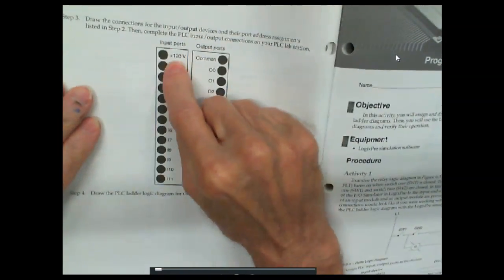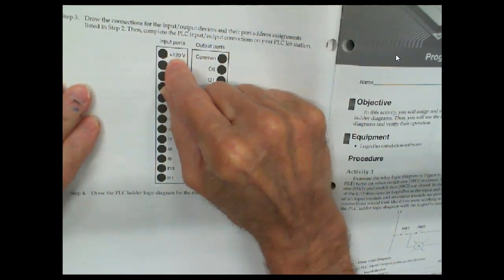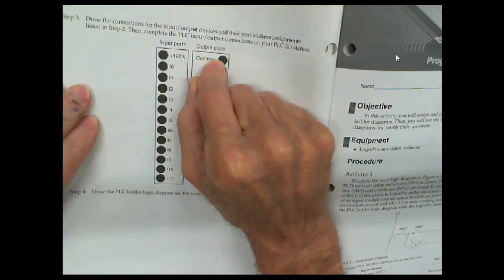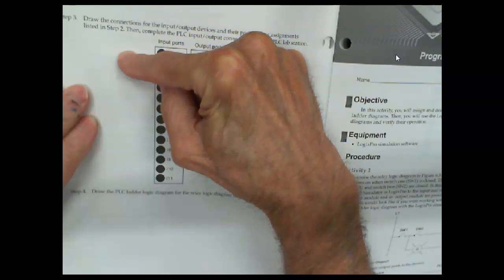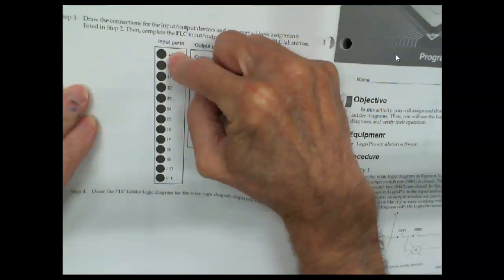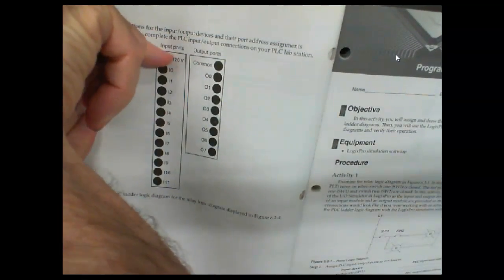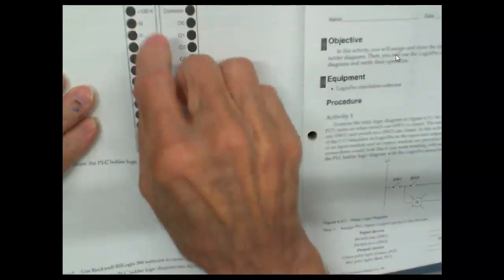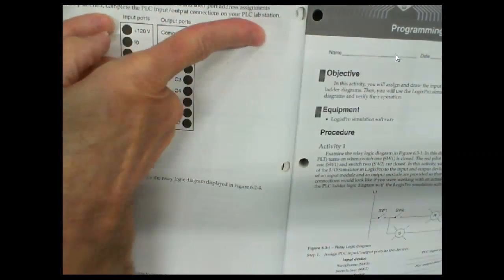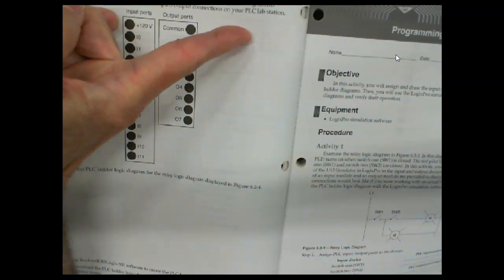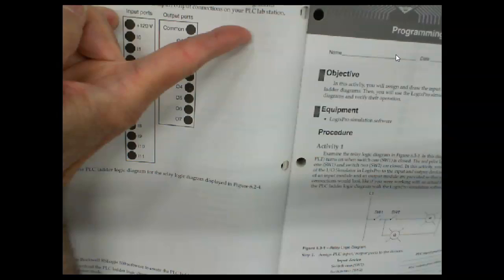This is what that guy's done. You're going to mark this out. You don't have to write common up there. The common's okay over here. And then you're going to draw that out and draw that power supply the way we've been showing y'all, right? We're running sinking input, so the minus has got to point toward this way. And then we're running sourcing output, so the plus. So those batteries are going to be pointing, the minus is going to be pointing toward the left. I mean the right, I don't know the difference.